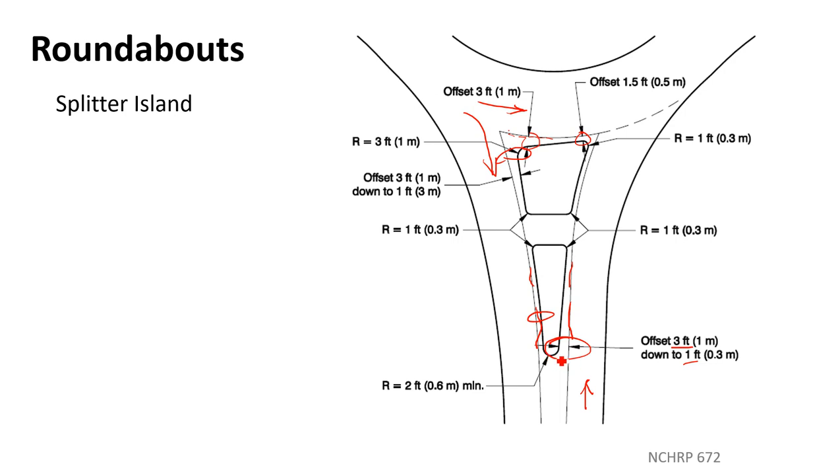And then we've got typical radii. I wouldn't hold strong and fast to this 2 foot suggestion here for it. It just depends on how big your island still is when you end the island. All right, so if this is still 8 feet wide, you're going to use something bigger than a 2 foot radius. You'll probably use a 4 foot radius, right? Because that'll match it just perfectly through there. So it just depends on what the shape is, how big your offset is here, whether it's a multi-lane or not roundabout through that, right?